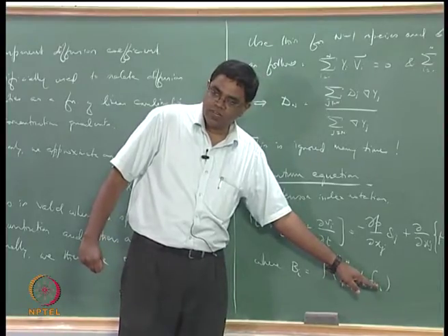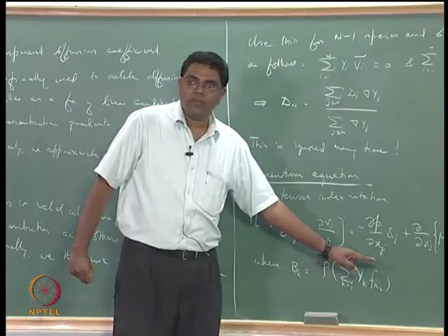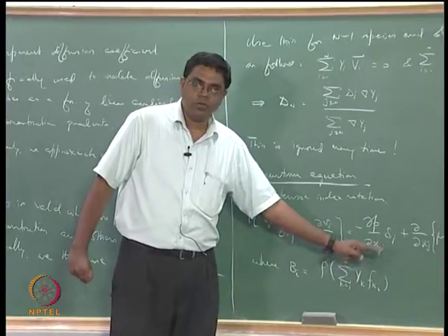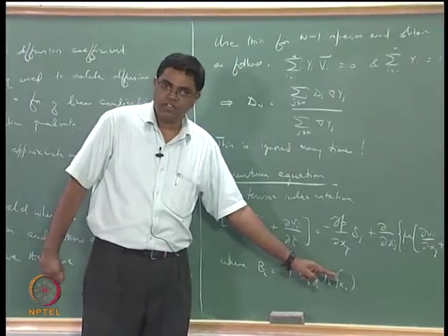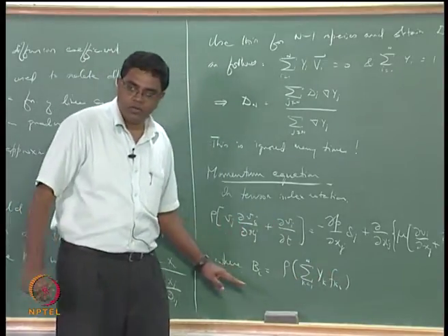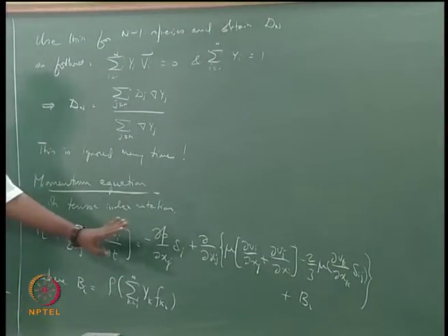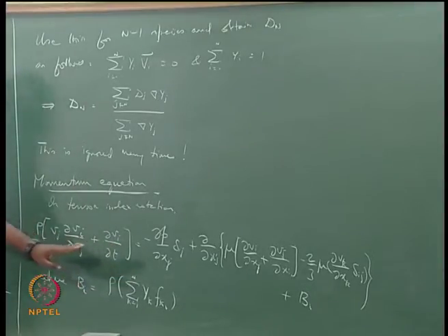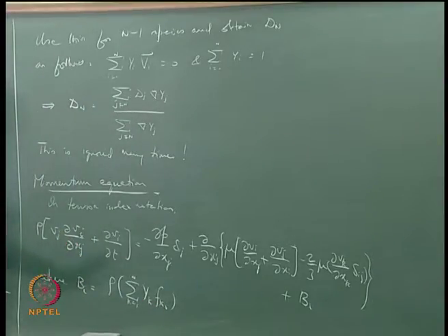So in this case it is the ith component of the kth species body force, the ith component of the body force per unit mass of the species k. It is sort of like acceleration, we went through this some time back. Times its density, it means that this is done per unit volume. This equation is valid at a particular point on a per unit volume basis. That is the reason why we multiply by density, because per unit mass times density gives you per unit volume.